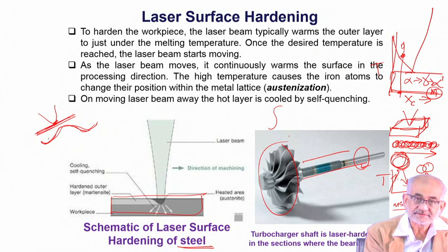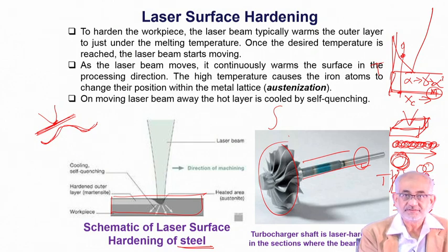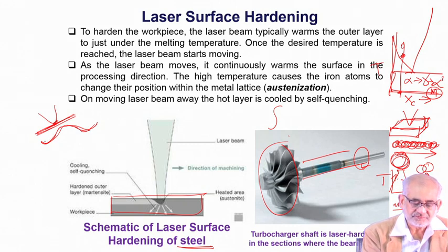Using that CAD trained beam delivery system, even if the contour or the shape changes, I can still make the beam move up and down exactly to ensure that the focus point remains at the same position with respect to the surface.